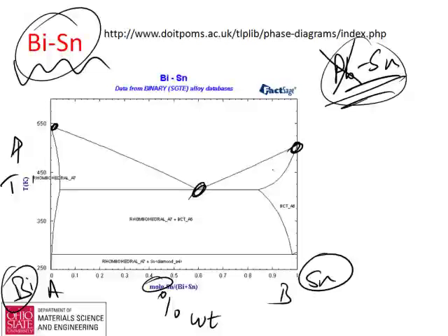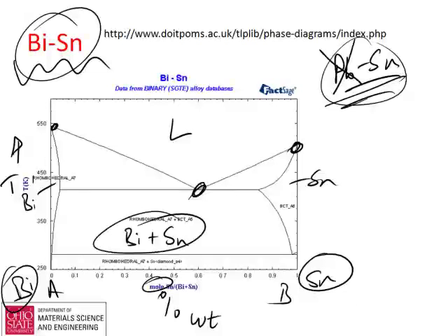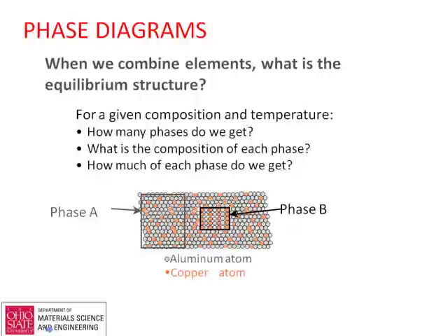And you've got different phase regions here, where this is liquid. This would be pure bismuth phase. This would be pure tin phase. And this would be solid bismuth plus tin, and it's basically a mixture of two solid solutions. So this is maybe a level of complexity you don't want to get to, but this is the way the real world is. It's not just element, mixture, compound, solution. This is a mixture of two solutions, and this is very, very common in materials science. It's something that I think is teachable as well, but this is mostly in the spirit of making you smarter than your kids.